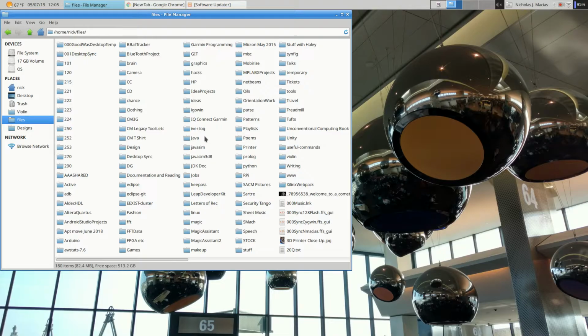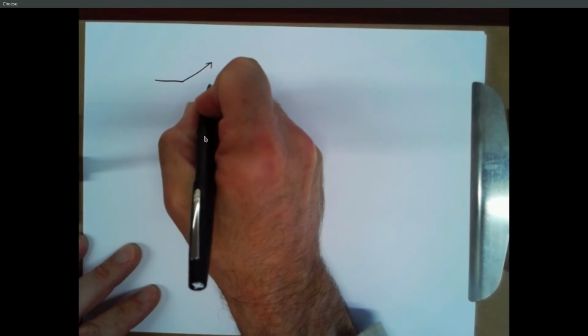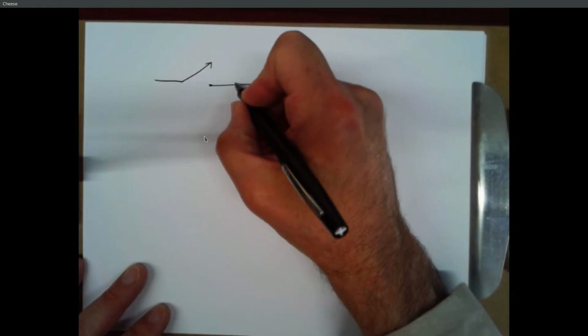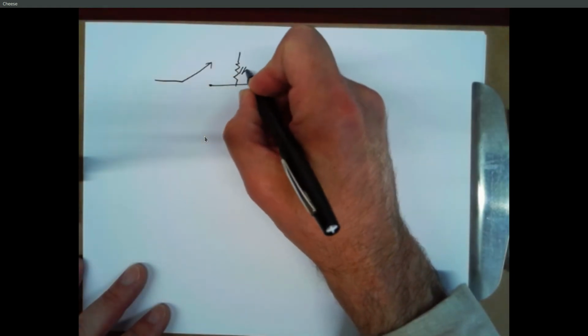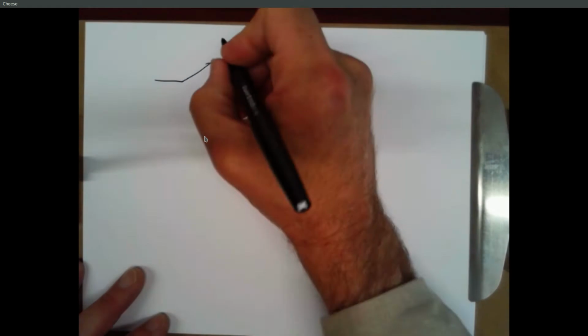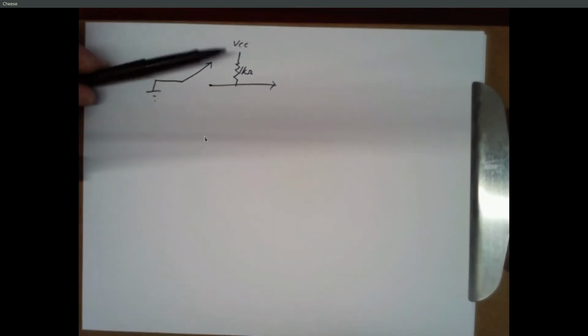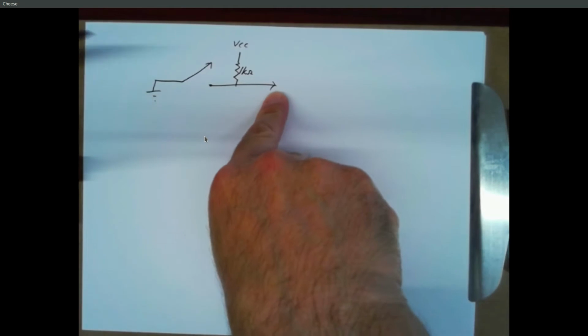And the main thing to remember is when you want to hook a switch up, we have these normally open switches we're imagining, like our slider switches, right? So when you want to draw a switch, this is the standard symbol if it's normally open. And if we want to feed a voltage level into a circuit over here, our one and only correct way to do this is to use a 1 kilo ohm resistor, tie that resistor to 5 volts, and then tie the switch to ground, so that if we close the switch, this point here is connected to ground. This is a logic 0.